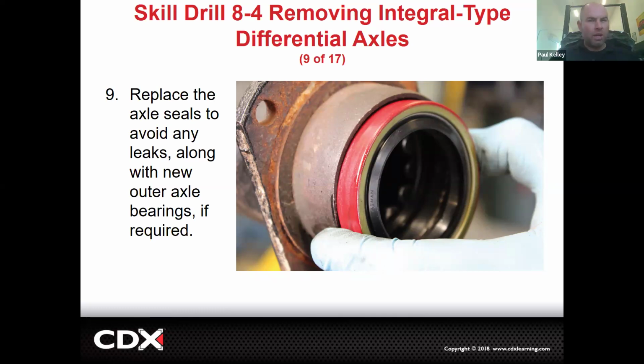So it's not a wheel bearing in a rear wheel drive with a solid axle. If it's got an independent rear differential, it could actually have its own wheel bearing because the diff is just the diff, and then a CV axle comes out, and then it has a wheel bearing. Okay, but if it's a solid, a live axle, if you will, there is no wheel bearing, it's an axle bearing, but the symptoms are the same. But the replacement's way different.